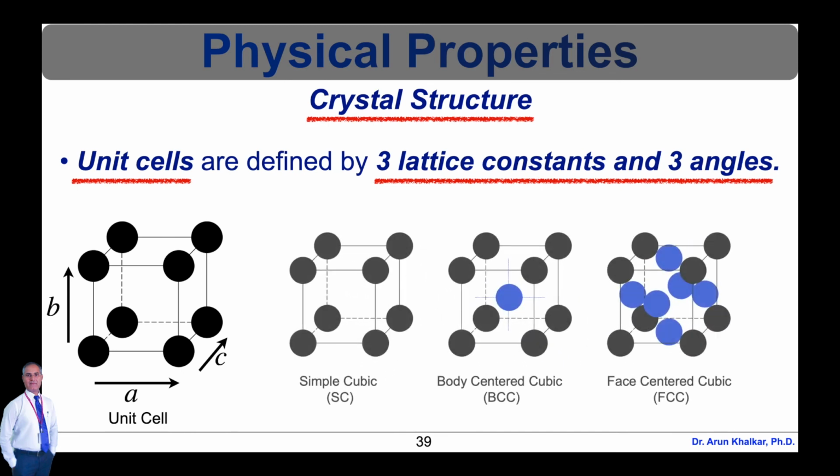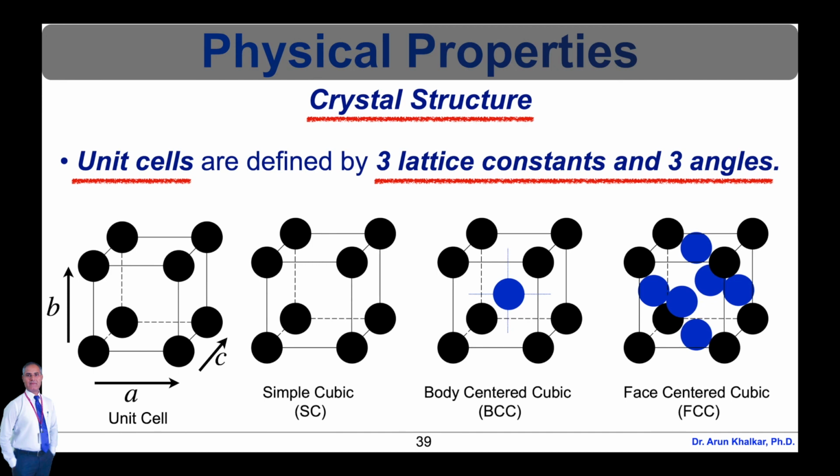the unit cell. Most metals in the solid form close-packed lattices as shown in this figure. For example, silver, aluminium, copper, cobalt, etc. are face-centered cubic, that is FCC. Magnesium, zinc, etc. are hexagonal close-packed, that is HCP structure. Chromium, lithium, etc. can form body-centered cubic, that is BCC, as well as FCC and HCP depending upon formation energy.